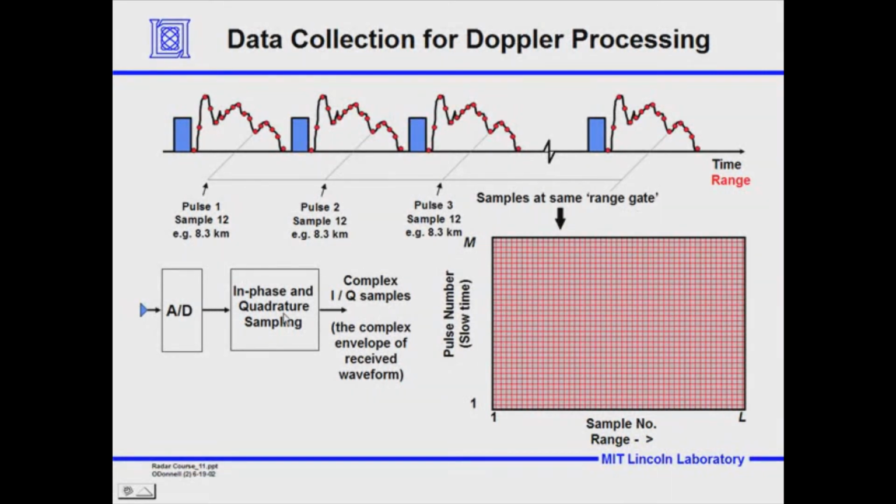And what we do is we take the data, since the echo coming back is really a vector. It's got amplitude and phase. It's an electromagnetic wave vector that's got amplitude and phase. We have to characterize that by 2 numbers. And the way we characterize it, much like you would say a force is a vector, you measure it along the x-axis and the y-axis, if it's a two-dimensional vector. And we characterize that by a real and an imaginary part.